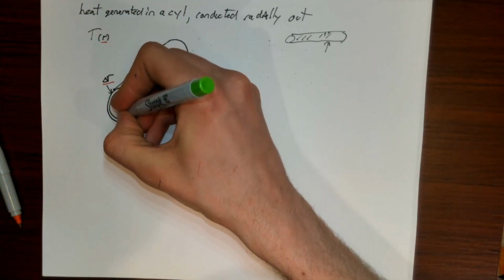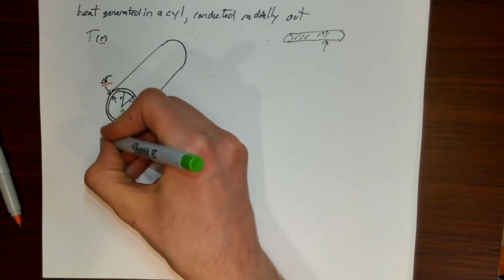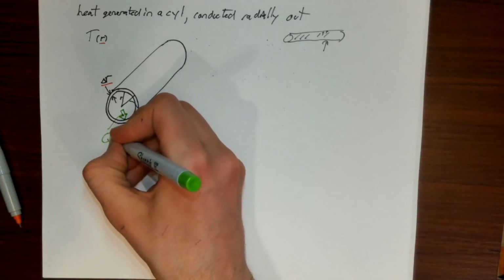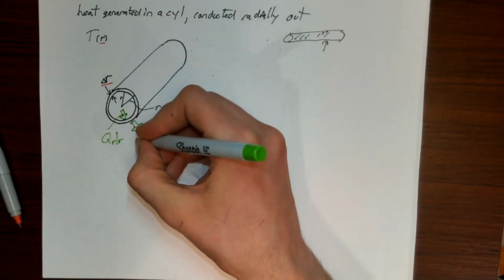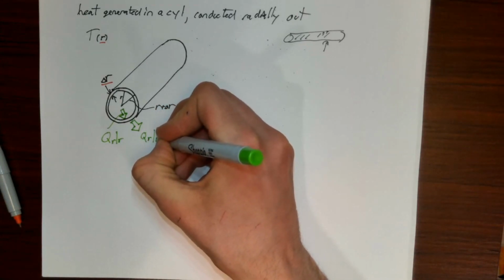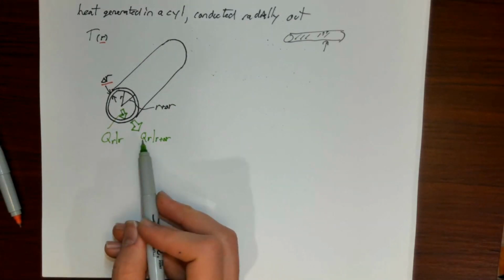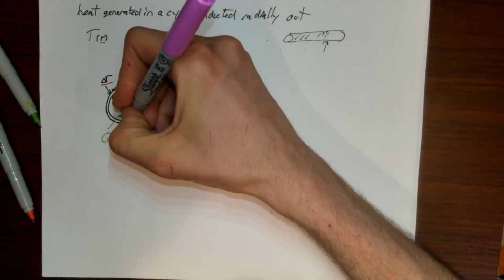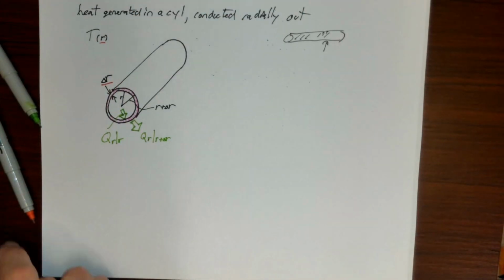The heat that flows into the inner surface would be Q in the r direction, evaluated at r, and the heat that flows out of the outer surface would be Q in the r direction, evaluated at r plus delta r. These two heats might not necessarily be the same as one another if heat is being generated within the volume of this shell right here.